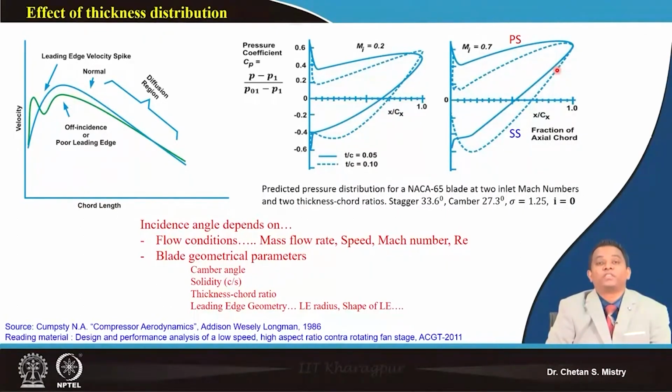Now at the initial stage when we are doing our design, we need to assume or select one of the aerofoils for our rotor or for stator. Then, based on what is happening on my blade surface, we need to visualize how my flow is behaving near the leading edge, and how it is behaving on my suction surface and pressure surface.